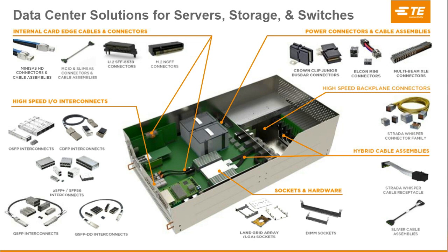If you go back a few years, the average power dissipation of a rack of equipment was below 10 kilowatts, and customers today are pushing 30 kilowatts with forced air. But as we move into the next generation, with more power dissipation, shorter distances, higher power densities, we're going to see a natural progression in the equipment manufacturers and the infrastructure to move to liquid cooling.